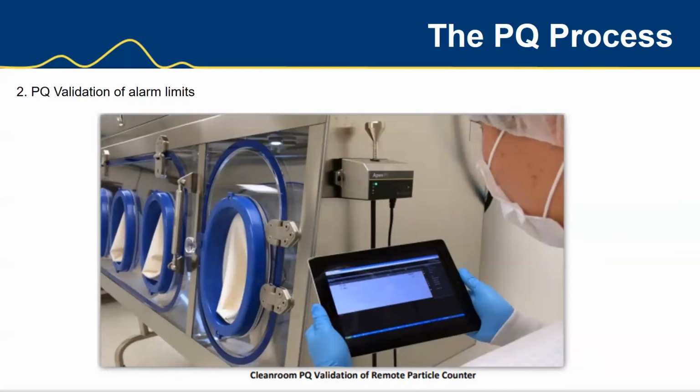A risk assessment process should be adopted to produce a science-based approach to setting your SPCs. What are SPCs? I hear you say. Statistical process control limits. You can have your alarms based on the probability of X out of Y events, turning into a detrimental trend that will affect product quality. Like getting back to that example I said about the 8 hours, 1 minute out of 8 hours where your 5 microns exceed 20 particles in one spike, is that really a detrimental issue? No, it's not.